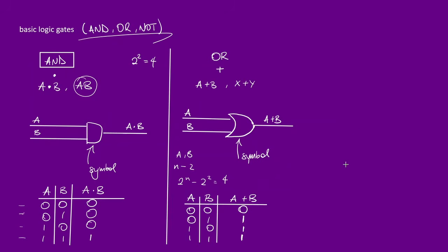You could even have multiple of these, okay? So the thing with logic gates is that it's not limited at all to 2 inputs, okay? The same principles hold as you scale it up. So let's say we had a 4 input OR gate, okay? Something like this, with an output this way. And we had W, X, Y, and Z, okay? If these were all 0, my output is going to be 0. Output, I need a letter, W, output K.